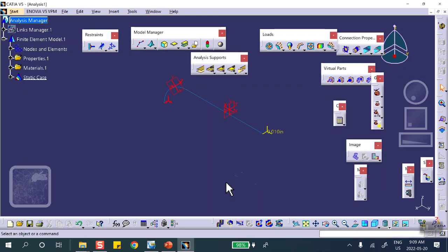There are other alternatives. You can probably take one point, say, don't come out of the plane. No displacement in the direction X, for example. You can do that. As long as you can make it work, no problem. But the easiest way to do it is just that rotation 0. If you don't like that, fix one point, not move in the X direction. I don't mean rotate, okay? Not move. Either way, deactivate that.